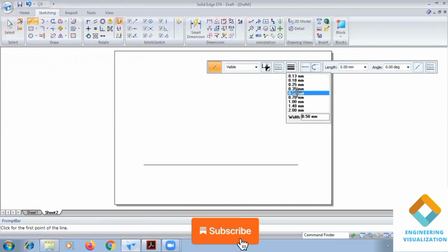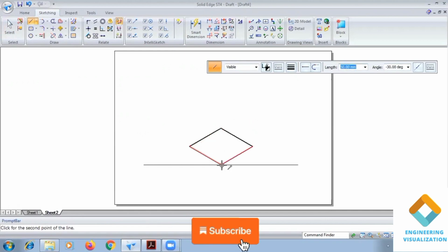So here please consider the angles. From this reference end, the length will be 50, angle is 30°. Again length is 50, angle is 150°, sorry. Then another line, again length is 50, angle is 210°. So like this we need to construct the box.